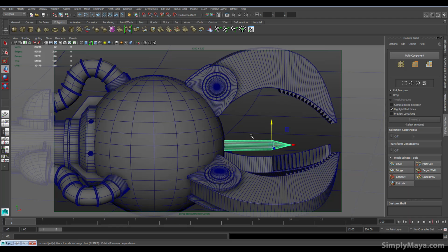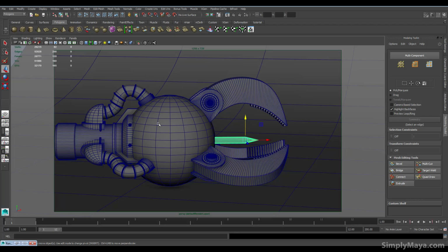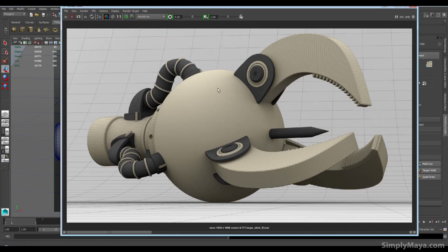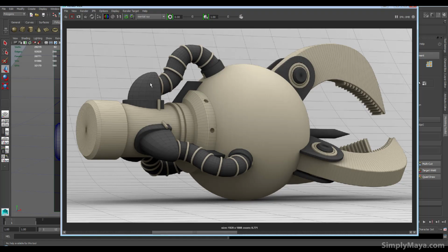Nothing to it really. What I really wanted to discuss in this part was simply rendering out of this, because you've probably seen the renders we have on the site. They look something like this. I really like this way of rendering out a model that I've just done. It looks pretty in my opinion, and you can see the wire on the objects that it's necessary to see it on. So this is contour rendering in Mental Ray. I thought I'd show you how I pulled this off and how this final render was achieved.